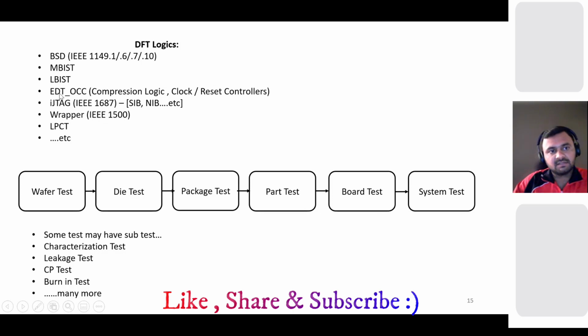And then you have compression. EDT is nothing but compression. In Mentor Graphics or in Tessent, it is called embedded deterministic test. Then we have OCC, which are clock controllers, and also reset controllers. We'll come to know in detail why we are using these. And then we have iJTAG, which is very famous nowadays. This is called IEEE 1687. This is the standard, called internal JTAG, Joint Test Action Group. We'll discuss more on this.